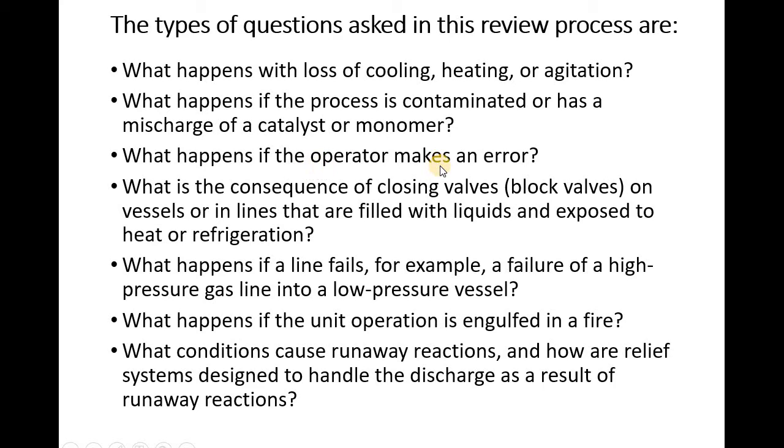What happens if the operator makes an error? Instead of opening, he's closing. And I have a story with that, but there's no time for that. Maybe one day when we sit in the class, I can spell that out. What is the consequence of closing valves? Okay, so you close valves, but you block, actually, you didn't close it only, it's fully blocked, fully closed on vessels or lines that are filled with liquid and exposed to heat. So you close that vessel and you heat it up.